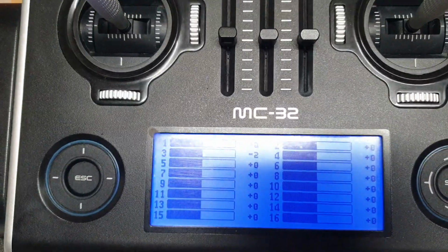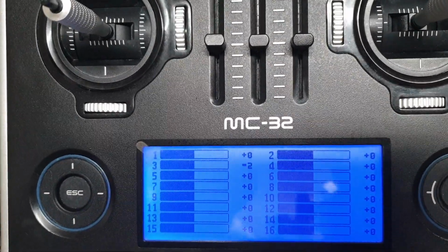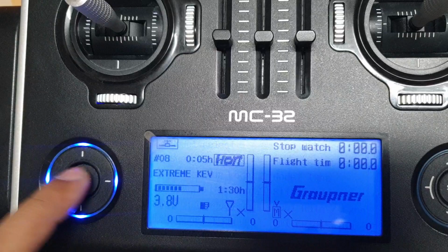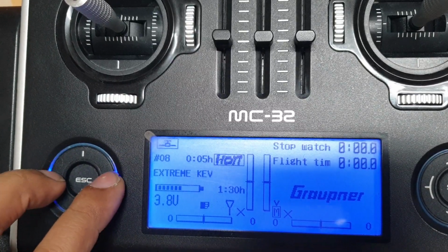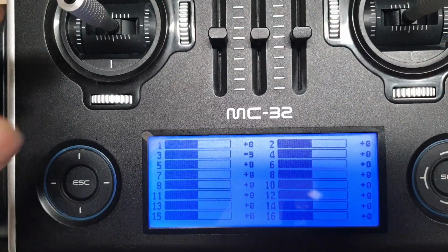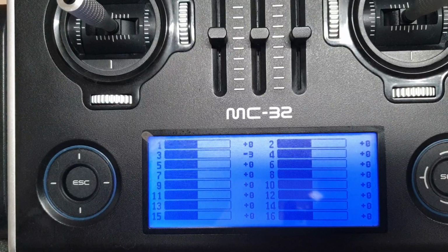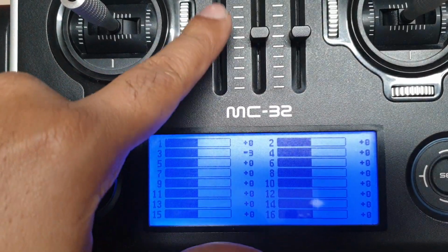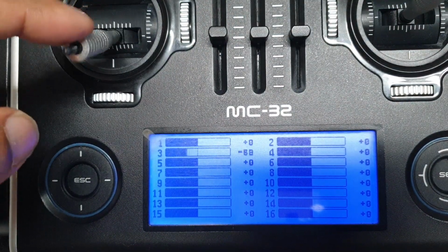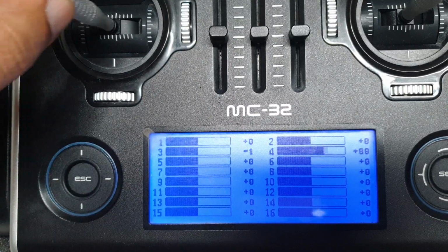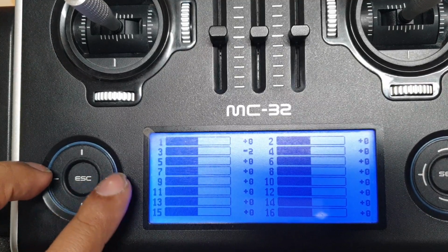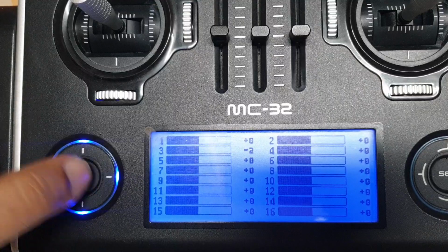So if you want to check any of the servos, to what channel they're connected, you need to go back to the home screen. Want to check what channel they are? Just press this, and this page will come up, and all the radios will generally have this page. What this page does, it has the channel numbers 1 to 16, and it shows you when you move a particular switch on your radio what it's connected to. Obviously, after 5 we haven't connected anything, but you can see this is number 3, and this is number 4, and this should be number 5, right? So 2 buttons on this side will bring you the bar graph. So let's go back again.